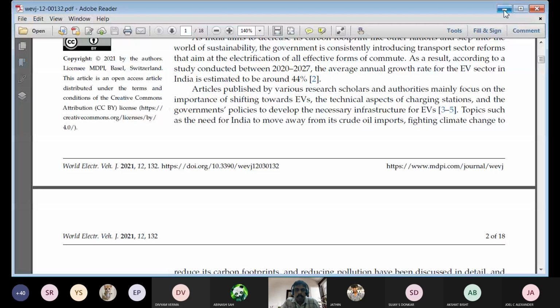Once the angles are determined, we have discussed the Page-Angstrom method to determine solar radiation. The Page-Angstrom method is only a rough estimation. Global radiation we can get in kilojoule per meter square per day using locality constants A and B, the amount of extraterrestrial radiation H0 calculated by another equation, and the sunshine hour length, that means how much sunshine is there in a day. Average sunshine you will be given, maximum you can calculate based on the sunset hour angle, omega s.